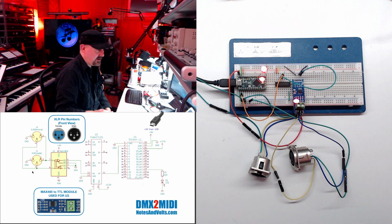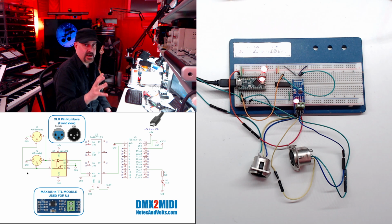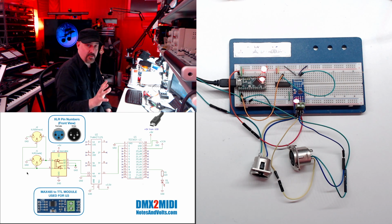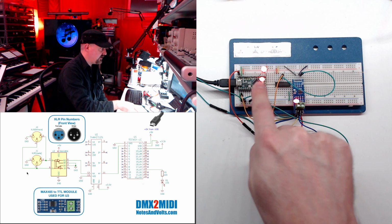the other end. Now, if you look on the other side of this board, there are 4 pins. There is DI, DE, RE, and RO. What does that stand for? The DI is the driver pin, and you can think of that as the transmitter pin. That's going to send signals out. Since we're only receiving signals with this circuit, we're not going to use that pin. The RO pin is the receiver pin, and that's going to take the signals we get from here and output them into our Teensy board.